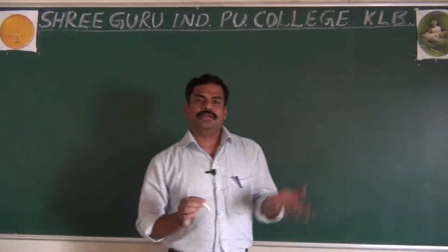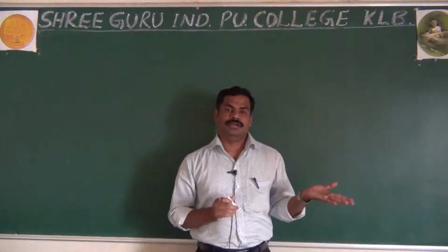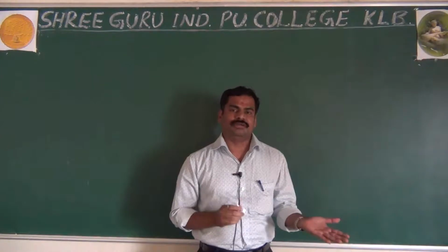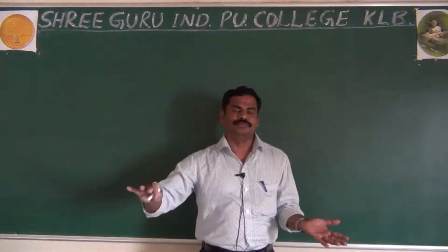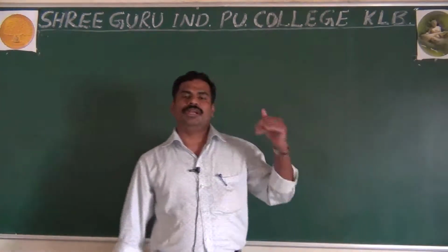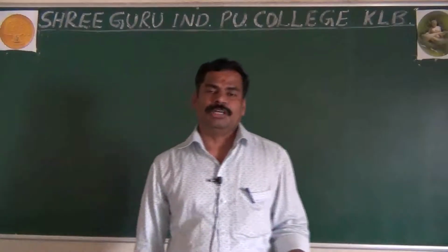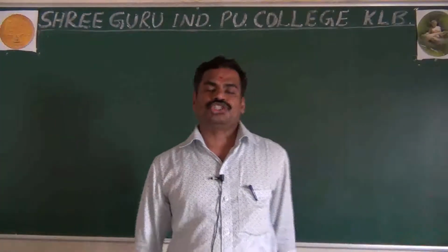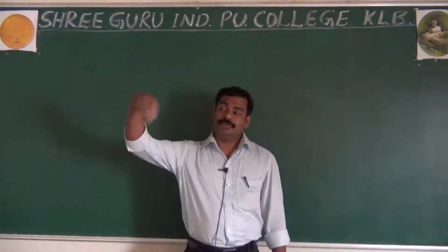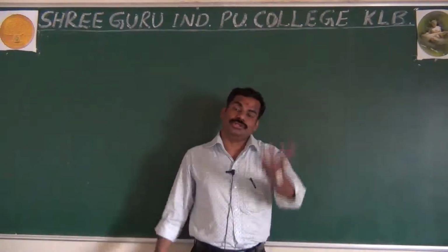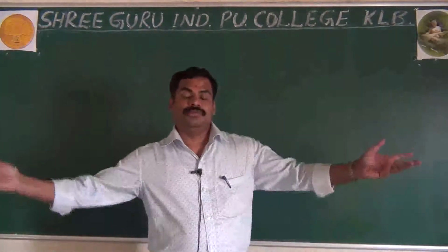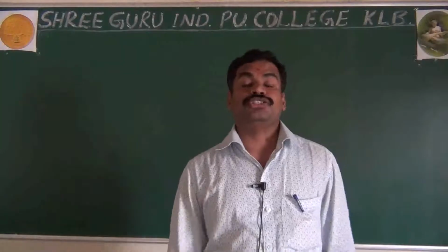It means, as I said, you are applying some input signal, and that input signal has some amplitude. If the amplitude is very much less than the Q point value of a transistor, that is your small signal amplifier. If the amplitude of the signal is more than the Q point value of the transistor, that is your large signal amplifier.